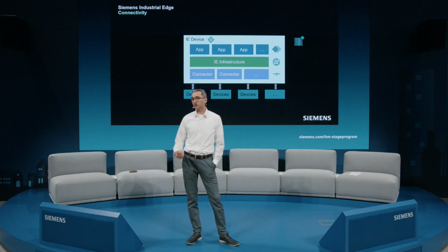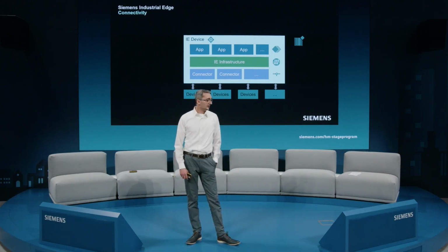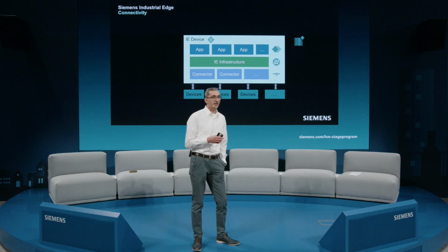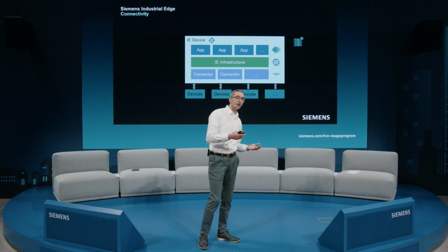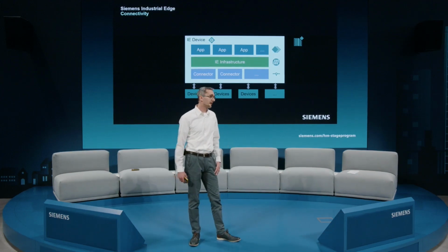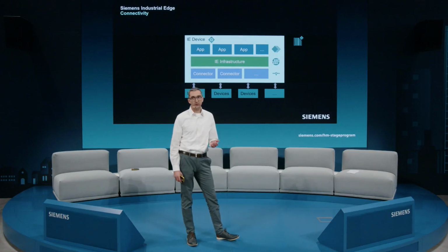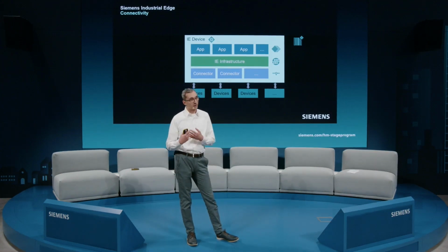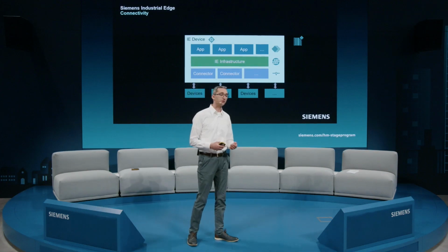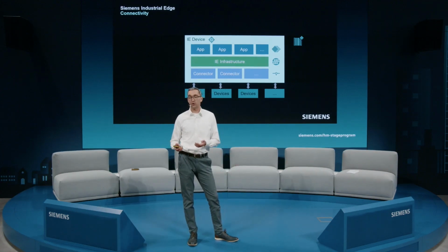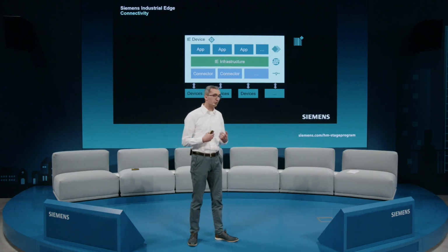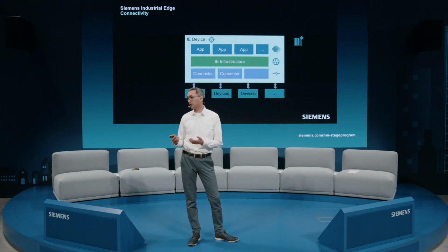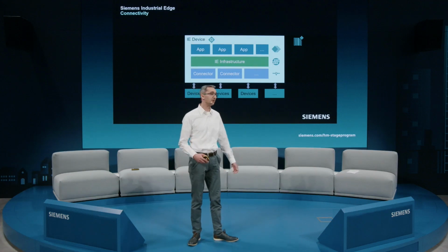The connectors are a special kind of industrial edge application, and they are responsible for communicating with the field devices with one specific communication protocol. They are able to get the data out from the field devices and provide this information to the applications in the north. The applications in the north are doing any cool stuff based on this information or parameter values which are provided by the connectors. For example, create dashboards, perform predictive maintenance, provide the data in an OPC server, or just push them to any further application running in the cloud.